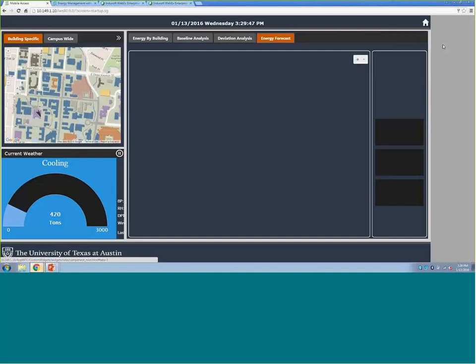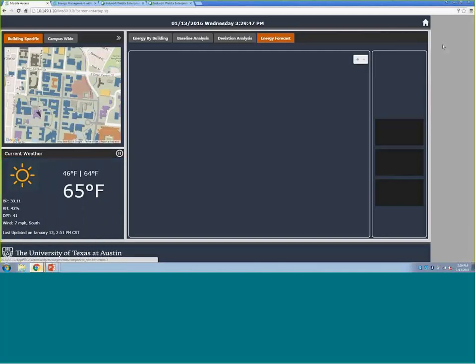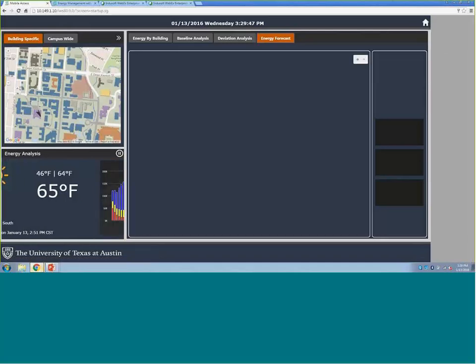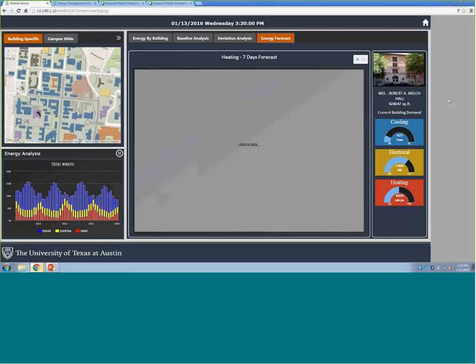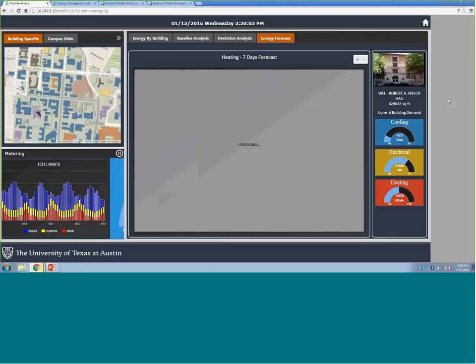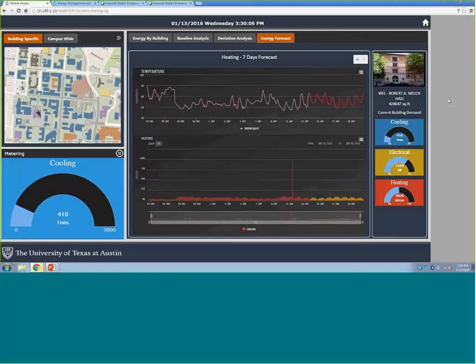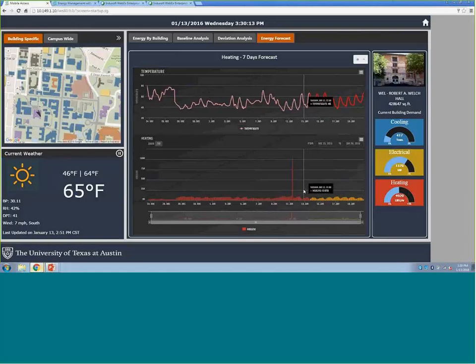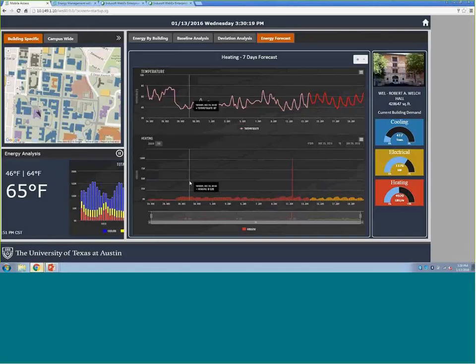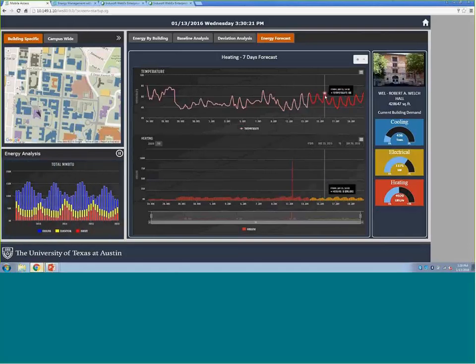So UT partnered with a weather provider company, where you are able to receive not only the live weather information that you are displaying here at the bottom, but also the history of weather and the forecast of weather. With this weather data and 3 weeks of real energy consumption, hourly, a lot of points here, we are able to find a mathematical model for this building, and then using the forecast temperature, forecast the energy use.